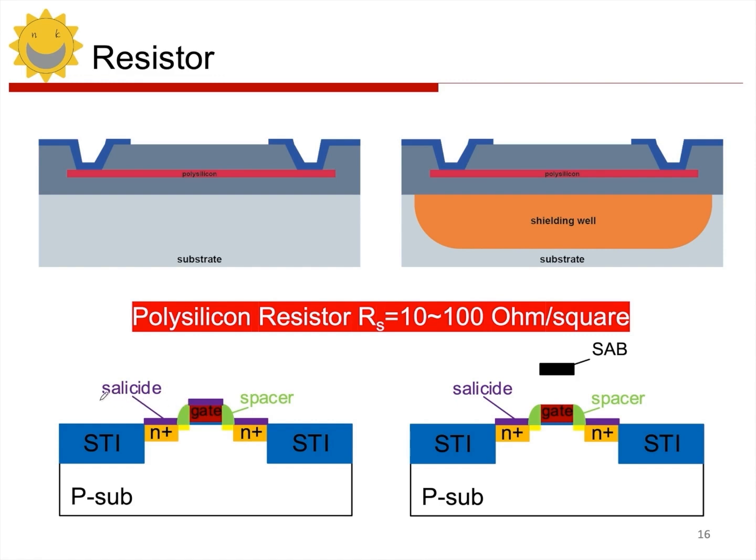We want to use the gate as a transistor. When used as a transistor gate, its resistance should be small, so this is a material with relatively low resistivity. The purpose of covering it is to reduce what? To reduce resistance, right? I can make the connections to the source and drain better. So, with this, we can lower parasitic resistance.